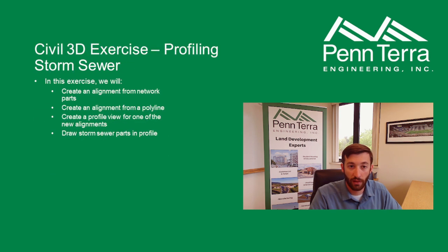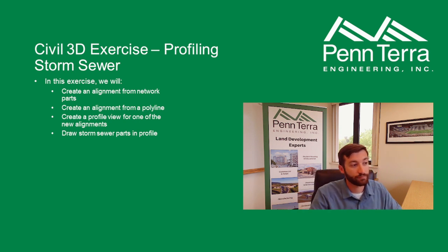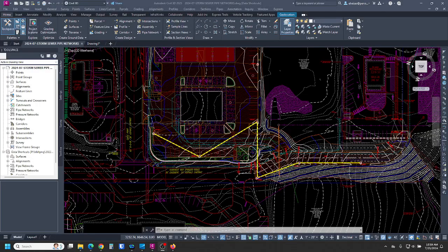So next exercise we're going to do is profiling the storm sewer. We're going to make our alignment from the network parts. We are going to draw a profile view for the new alignment, and then we're going to draw the storm sewer parts in a profile. So we'll flip over to CAD, and we're going to just continue on from the network we had the last time.